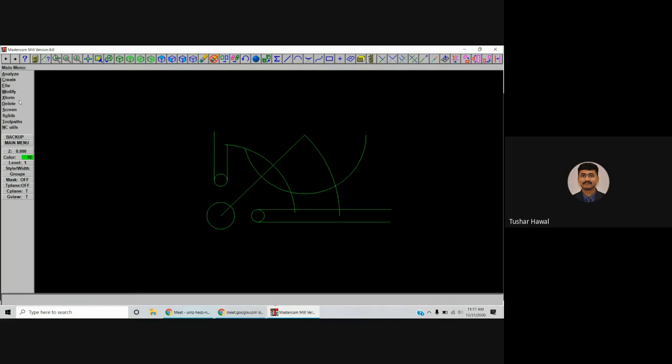Yes. Now I'll go to trim option again, modify, trim two entities. I can retain now this portion and this portion. Again, it is trimming this portion. So there is some misbehavior from the software. So I'll use the same option again, modify, extend. Length, I will give some bigger length of say maybe 5. Extend this quickly.